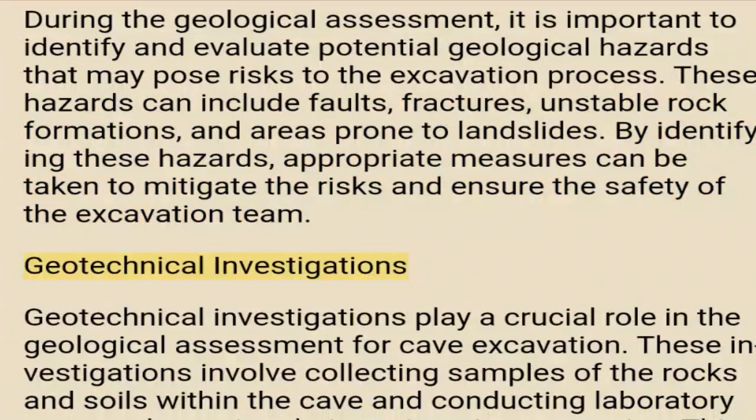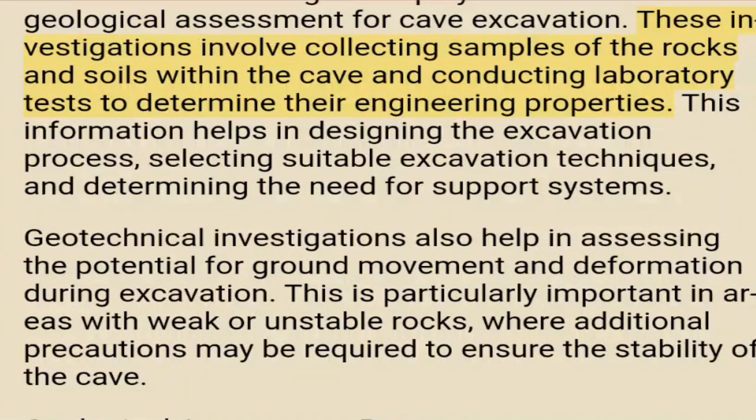team. Geotechnical investigations. Geotechnical investigations play a crucial role in the geological assessment for cave excavation. These investigations involve collecting samples of the rocks and soils within the cave and conducting laboratory tests to determine their engineering properties. This information helps in designing the excavation process, selecting suitable excavation techniques, and determining the need for support systems. Geotechnical investigations also help in assessing the potential for ground movement and deformation during excavation. This is particularly important in areas with weak or unstable rocks, where additional precautions may be required to ensure the